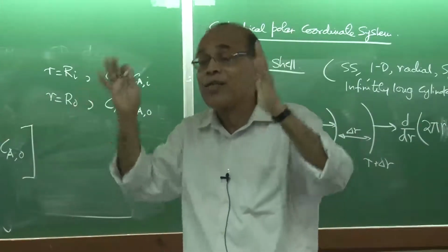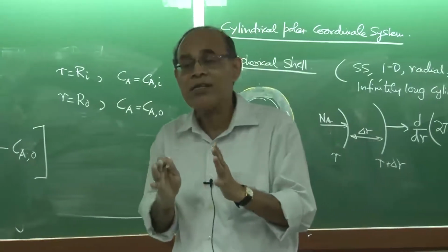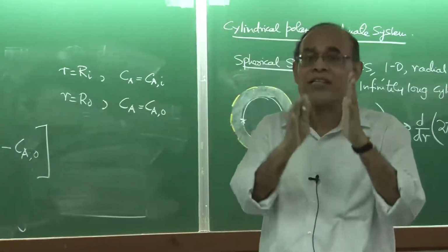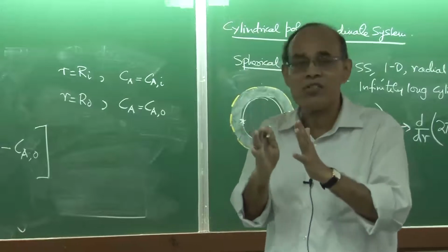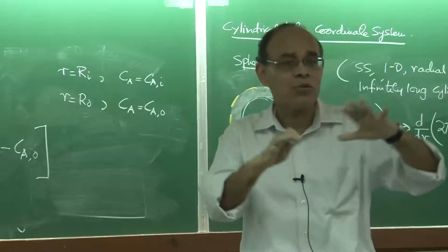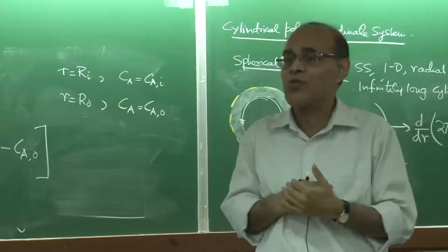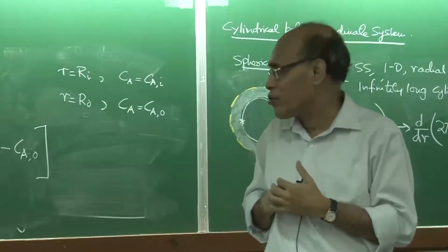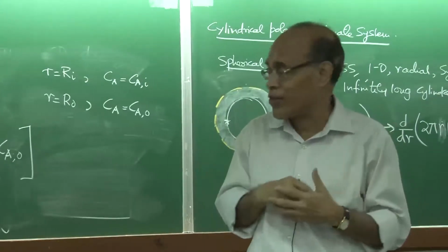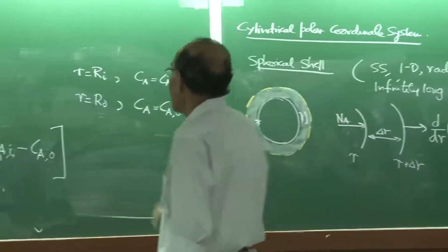For 1-dimensional unsteady state pure diffusive mass transfer, semi-infinite geometry as well as an infinite slab, these solutions are going to match exactly with the error function solutions and the infinite series solutions that I gave you during my discussion of heat transfer.